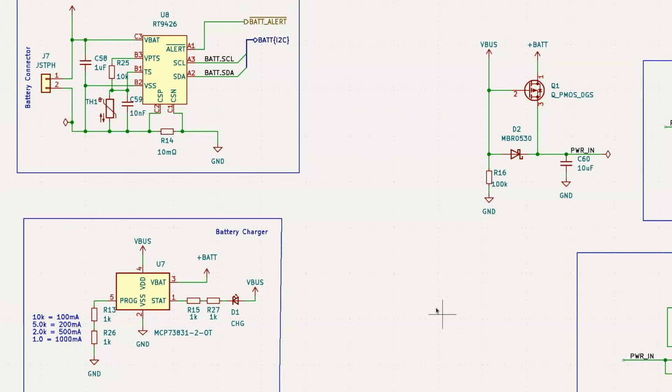Supercaps are fun, and I know a couple people that have done some stuff in that space. And technically, we could experiment with that without even changing anything, right? Because all this battery charger does is send power at a pre-programmed constant current, which is controlled by these two resistors here, and it cuts it off at a certain voltage, which would be exactly what you need to feed a supercap. Exactly.